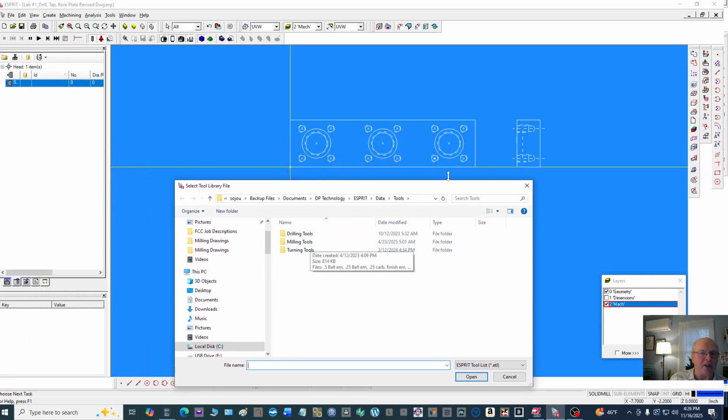So in the first case, I'm going to be doing a face milling operation on this first, because we're going to do this project in a different way than we did in CNC 1. We're going to put this in a vise. It's going to be down on top of parallels, 1/4 of an inch into a vise. And then we have to allow for extra material for that to happen.